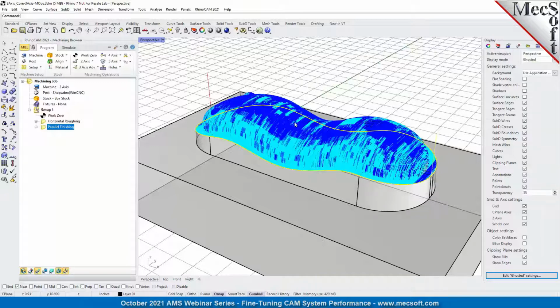In support, we look at a lot of people's screens and we see how they work, and a lot of people have a lot of geometry on the screen that's not needed. You probably already have your geometry separated on layers. Turn off those layers that are not affecting what you're working on. That will decrease your toolpath generation time. Just keep it clean, keep it simple, and keep it fast.